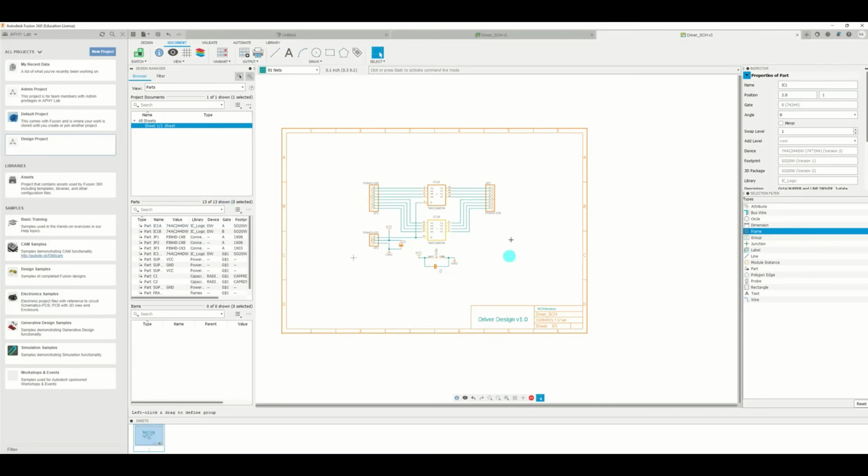The next thing to do, which would be the topic for the next session, would be to create our PCB from this one by creating a new one and switching to a PCB layout. But you have to link the PCB to the schematic. It's better that you do that in the project itself.